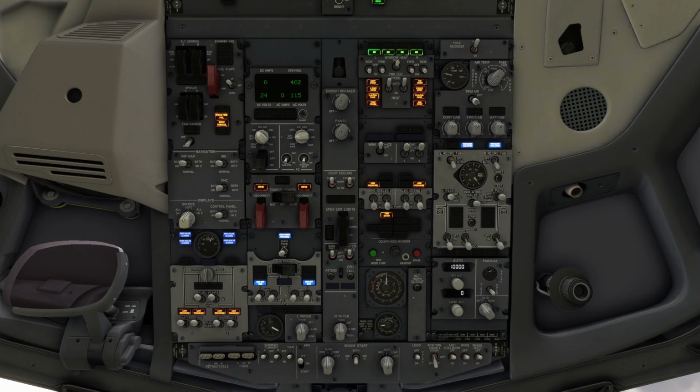Once that is out of the way, we're going to want to consult SimBrief. We're going to want to take a look at the cruising altitude. So for today's flight, the cruising altitude is 37,000 feet. Like I said, you can check this on SimBrief. That's all very straightforward. You'll see that under the title initial altitude. So very good. Our cruising altitude for today is flight level 370, which is 37,000.